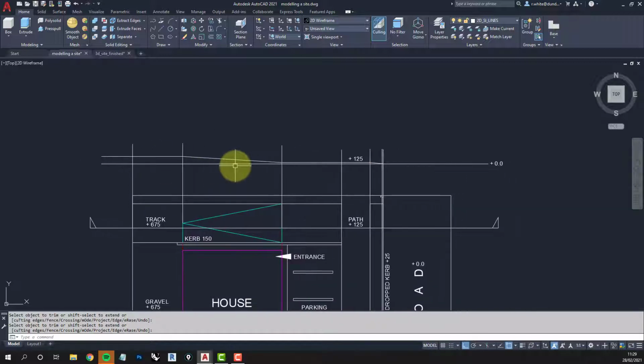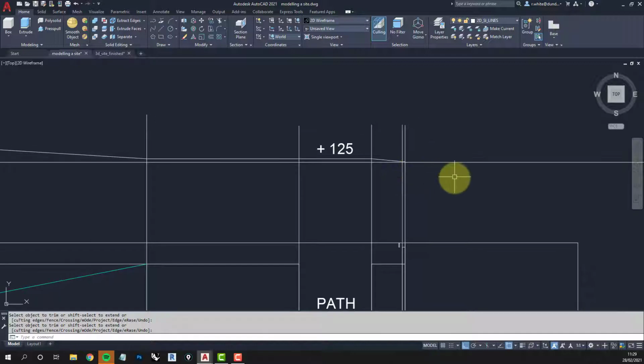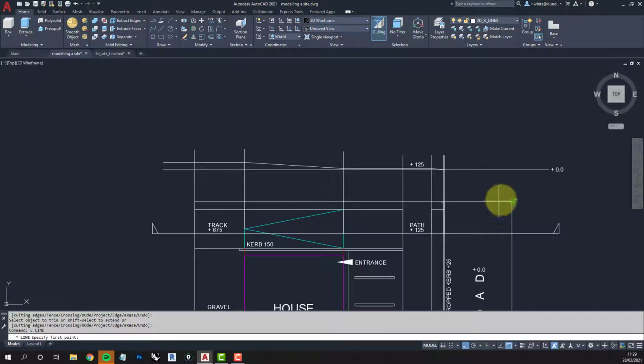Okay. Now to make it solid, we need a bit more base. We need a bit of base here. I don't mean musically bass. So let's make it the same shape as our model, and we'll say that we'll make the base 1000 millimeters thick. So we'll offset the datum downwards by 1000.